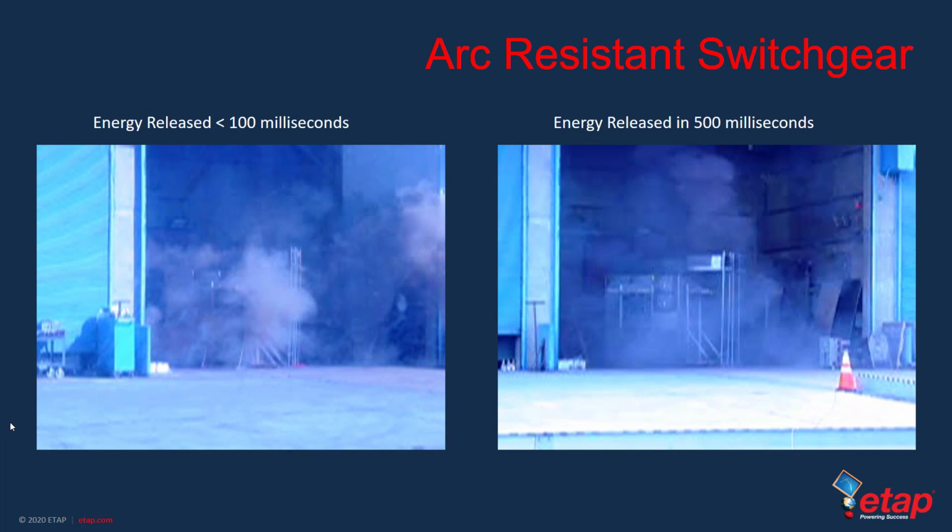The main concept that we're trying to understand from this video that we just watched is that when evaluating arc resistant equipment, we're trying to determine if the equipment can handle a certain amount of energy buildup internally. Just because equipment is arc resistant, it does not mean that it can handle any amount of energy flux per unit second. The pressure buildup is proportional to the arc power and time.